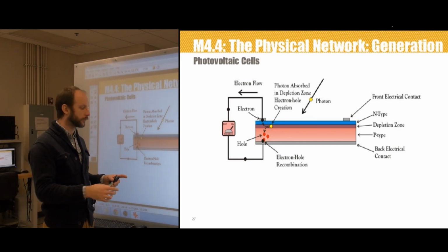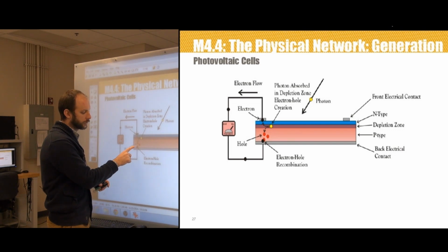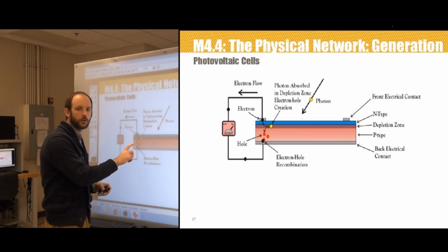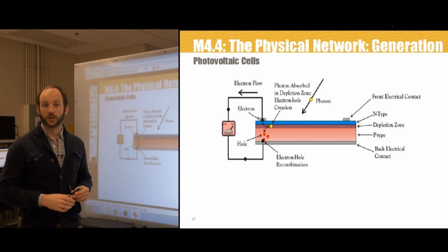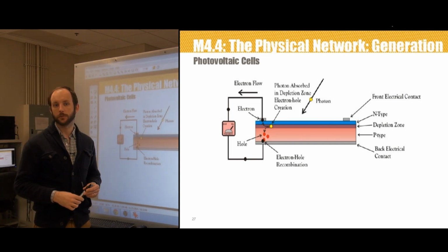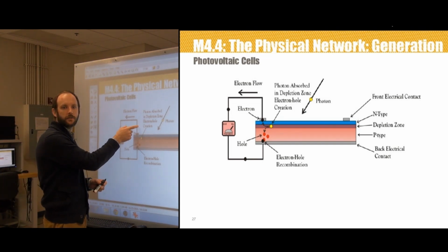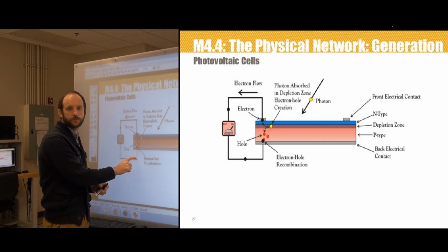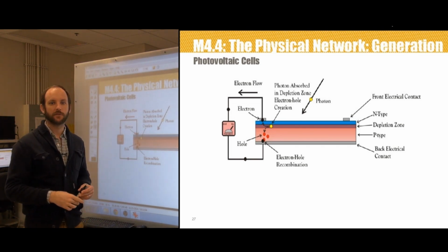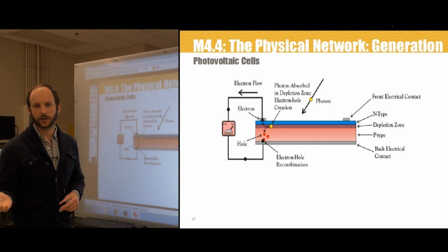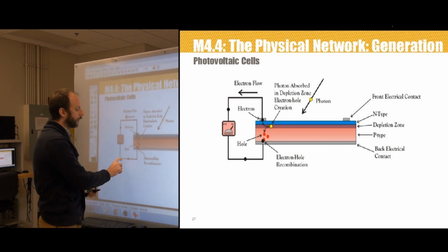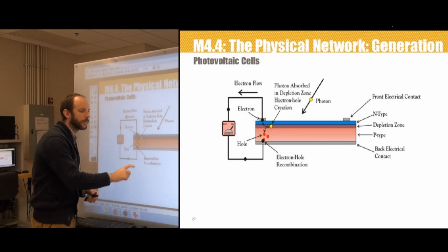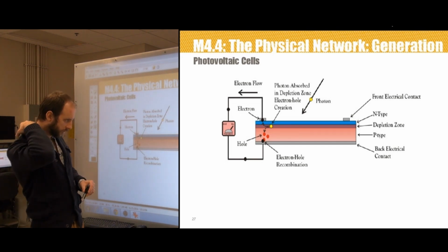This charge separation of these accumulated electrons and these accumulated holes creates a measurable voltage that can be used to deliver current to a load. If an electrical connection is made to the N-type and P-type materials to form an electric circuit, electrons will flow out of the N side through the wire, through the load, and then back to the P side. By convention, positive current flow is in the opposite direction to actual electron flow. So the current in a solar cell is said to flow from the P side to the N side, despite the fact that it's actually electron flow that's causing current to flow. So just to summarize, what happens?